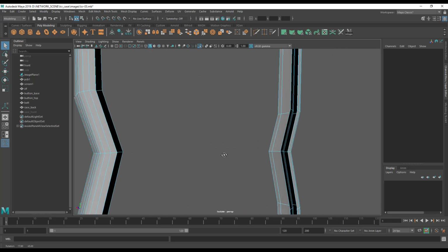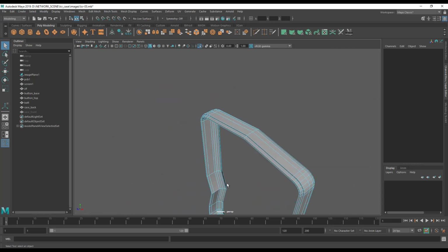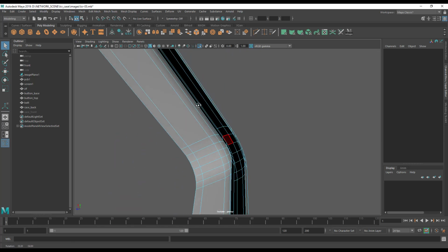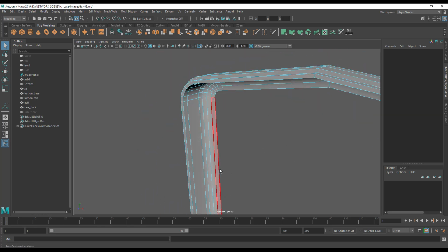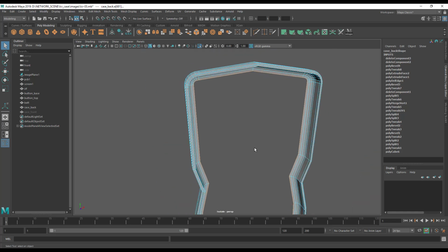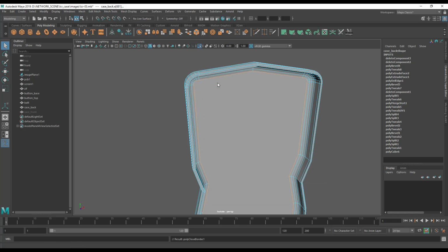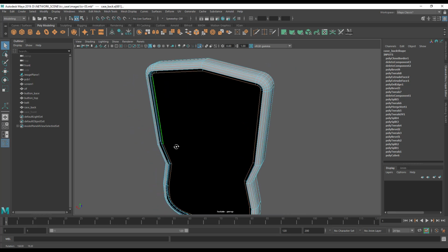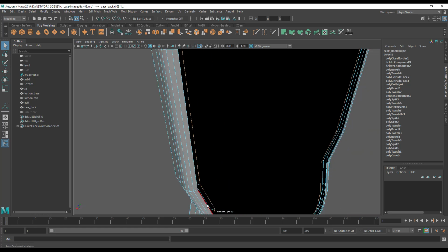So easy enough to get those back, by the way. We're going to select the edge, and you should now be able to see, this is another good point, that we've kept a uniform 2mm thickness all around, which is nice for us. I like it. So let's come in here and select this edge, select the whole edge, and we're just going to go to mesh, fill hole. There it is. This is a command that I really don't use a lot. And 3, you can see we're down. We've got no non-manifold geometry, no big warning down here. We are golden.